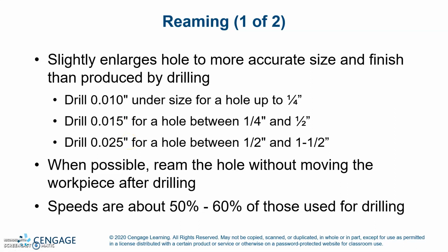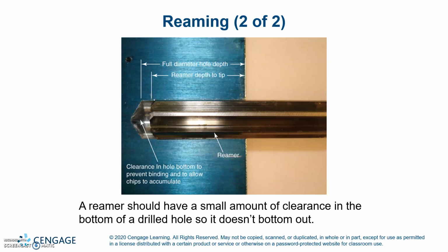When possible, ream the hole without moving the workpiece after drilling. Speeds are about 50% to 60% of those used for drilling. A reamer should have a small amount of clearance in the bottom of a drilled hole so it doesn't bottom out.